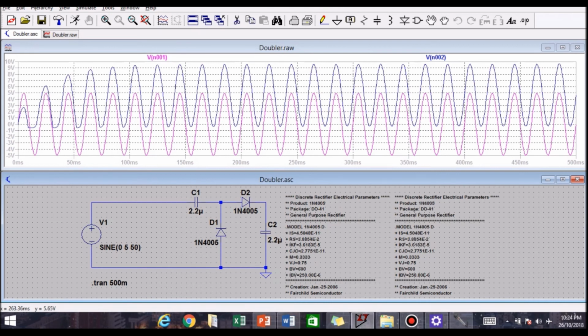Another piece of information: we can reverse the direction of the diodes and capacitors in the circuit. We can also reverse the direction of the output voltage, creating a negative voltage output. Also, if we connect the output of one multiplying circuit to the input of another circuit, we can continue to increase the DC output voltage in integer steps to produce voltage triple or quadruple circuits.